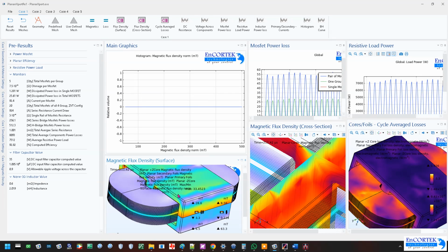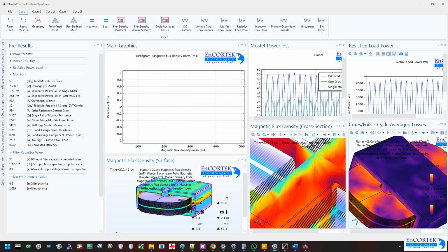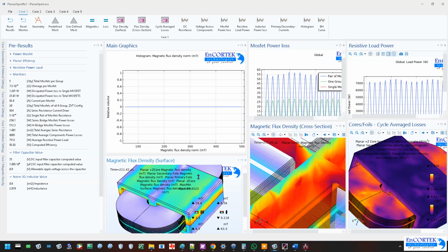So we know if we have the core only doing like 400 millitesla, and we have probably about 25% of 400 millitesla, that is fine. That is really good, right? So once it does not cross 50% over, where we are saturating the core so often, you can have one or two small spikes, but not a high percentage. The model, when I built it, worked here, but for some reason it didn't come across here, so I got to fix that code, which is not a problem, right?